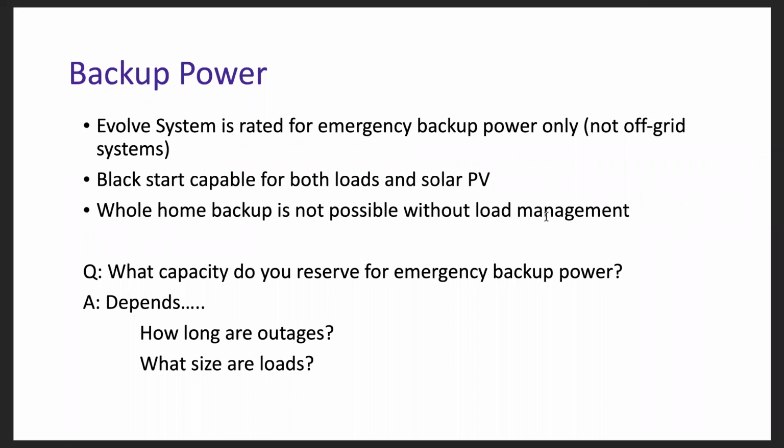A lot of people ask about whole home backup, and without getting into too much detail here, obviously whole home backup is not possible without some sort of load management. If you don't have some type of smart load control and a special interconnection and switching topology, then whole home backup really isn't possible.